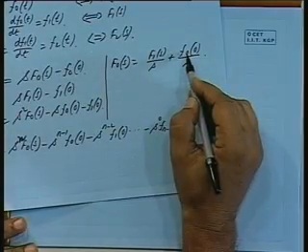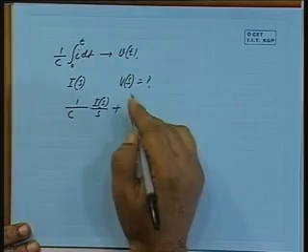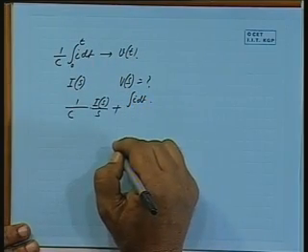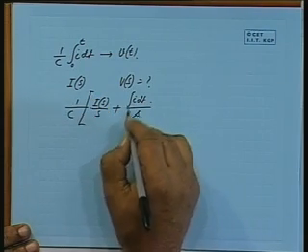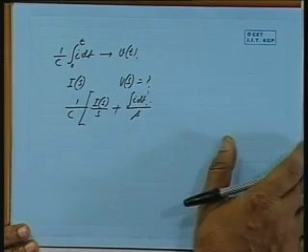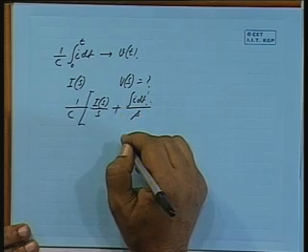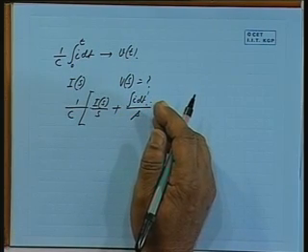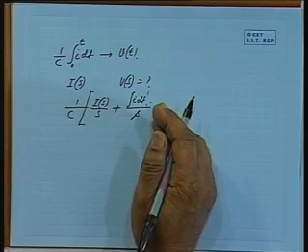What is f0? It is the integral of that. So, integral of i dt divided by s, and this is to be evaluated at 0. From where do we start? From 0 minus to 0 plus, or basically whatever has been there before the counting of time, before t equal to 0.